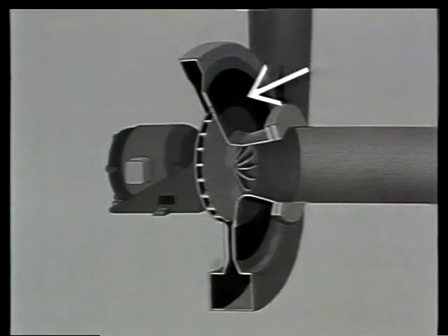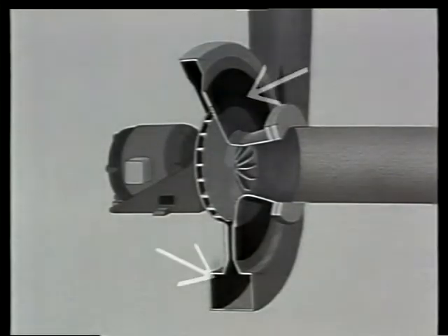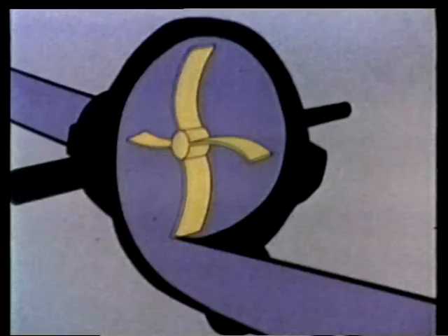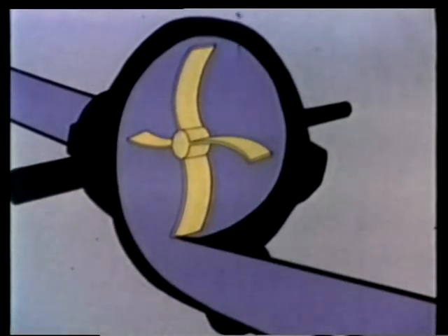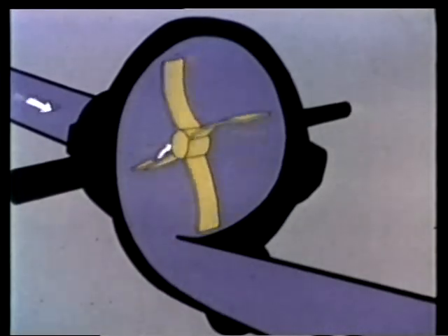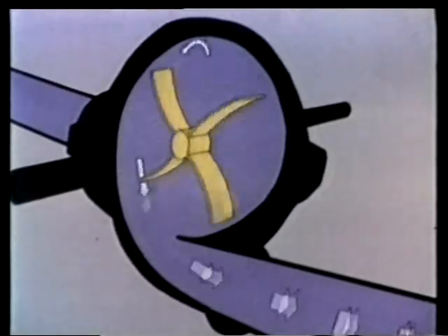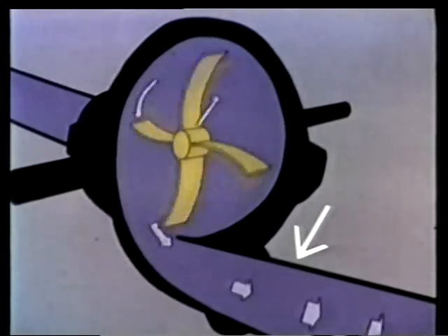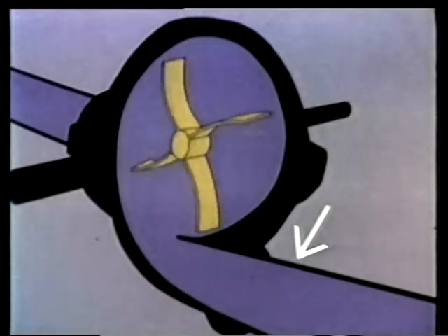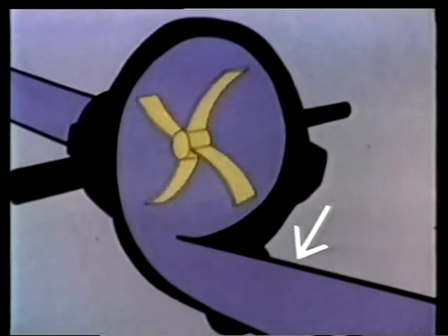Around the outside of the casing is a wider section called a diffuser. Following the diffuser around leads us to the volute, a continually widening discharge pipe. Now let's look at a simplified version and see the parts in action. If we look inside the impeller, we can see that it's composed of several large curving blades. As the impeller turns, air enters the suction eye and is spun outward by the rotating blades. This is how the air picks up speed. The fast-moving air is pushed around the circumference of the casing till it reaches the volute. Here, where the pathway gets larger, is where the air begins to slow down. This increases the air's pressure.